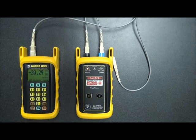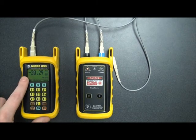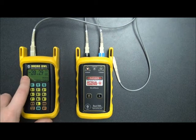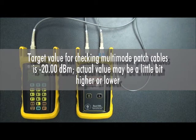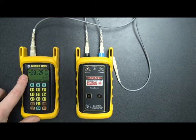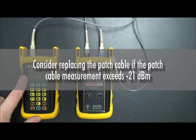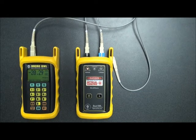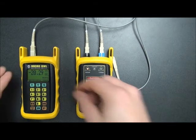Okay, now you can see that we have a reading of minus 20.29 for 850 nanometers. Now remember, our target value is minus 20 dBm. This is where our multimode sources get calibrated at, and the calibration occurs through a mandrel wrapped cable. So you can see that we're very close to minus 20. Now if we're reaching minus 21, then we want to start considering replacing the patch cable. But for now, this is a good reading. So now we know that our 850 nanometer reference cable is okay.